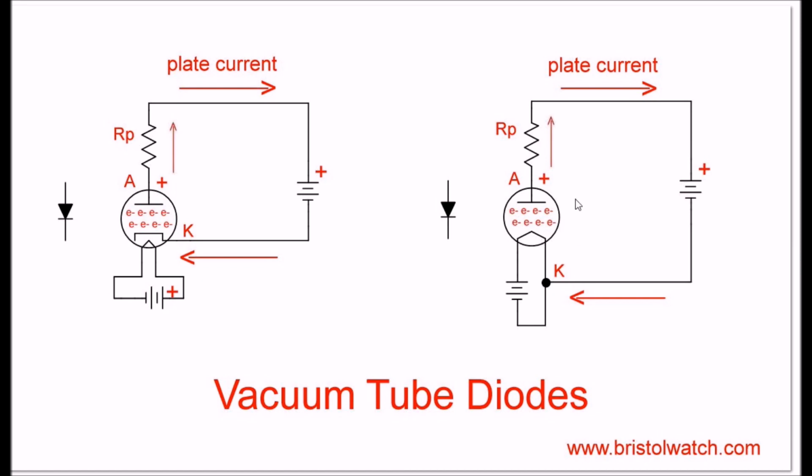So this is a diode. The cathode here corresponds with the cathode on your diode. The positive anode is the anode on your diode. Your current flow, in actuality, in a diode, is against the arrow. The arrow is merely pointing to the negative material. These work exactly the same, and the current flow is negative to positive, and we're going to discuss power supplies in a minute. Again, this is the very same thing, it just has a separate heater for the cathode.